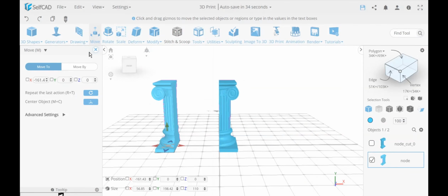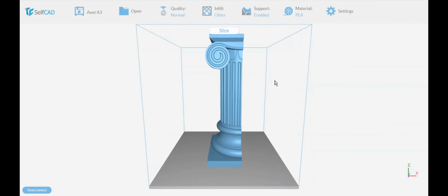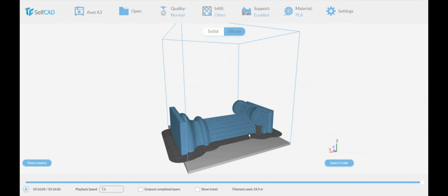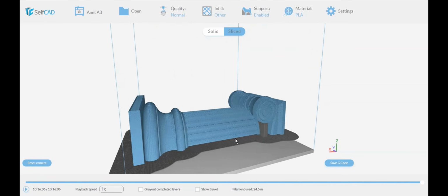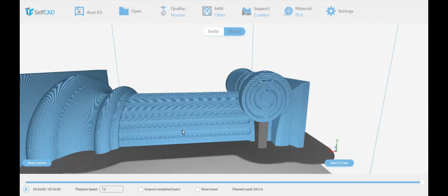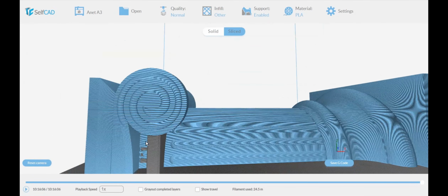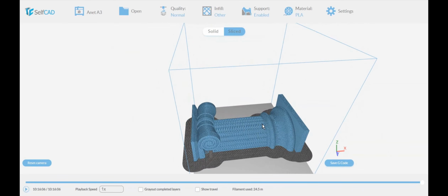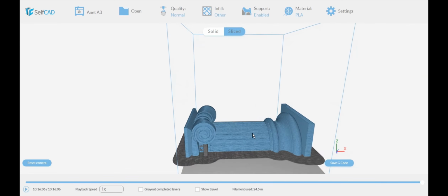So let's say I go now to 3D print with this one, I can just put this on the plate, put it like this, and now you can see I sliced it with the same settings as before, and we need support only here, only these overhangs over here on both sides, and other than that basically there's no support. Maybe a little bit of support inside, and that's basically it. So cases like this can solve a lot for when the printer is too small. You need to fit bigger objects, so you need to split them, but sometimes you may need to create some adapters to be able to stitch them together, and that's a part of the modeling application. And sometimes it's just a way to avoid or eliminate support. And with the combination of SelfCAD's editor and slicer, you basically have everything to clean this up.